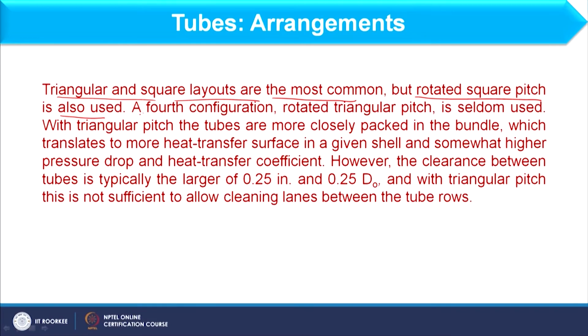Further, we have a fourth configuration, and that configuration is rotated triangular pitch, which is rarely used, but it is in use. Okay. So, with triangular pitch the tubes are more closely packed in a bundle, which translates to more heat transfer in a given shell and somewhat higher pressure drop and high heat transfer coefficient.